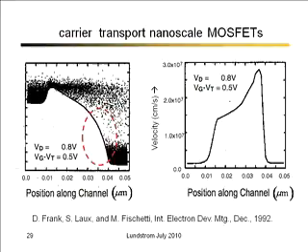If you look at these detailed simulations, you see the strong electric field at the drain end, and you can see that the velocity is very, very high. You increase the drain voltage, the velocity will get higher and higher. But what you'll notice is that the velocity back here has saturated. And the velocity there is right at this inflection point. That's where the velocity is saturating. As you increase the drain voltage, the velocity at the drain end gets bigger and bigger, but the velocity at the source end saturates at this V sub t. So that's how velocity saturation occurs. It occurs in these very small devices, but it occurs for physics that's very different from the way we understood it 15 or 20 years ago.